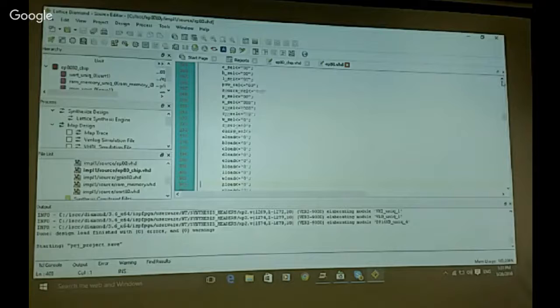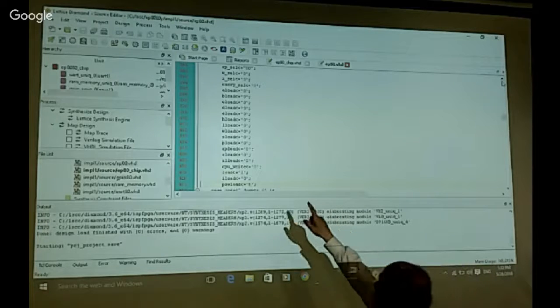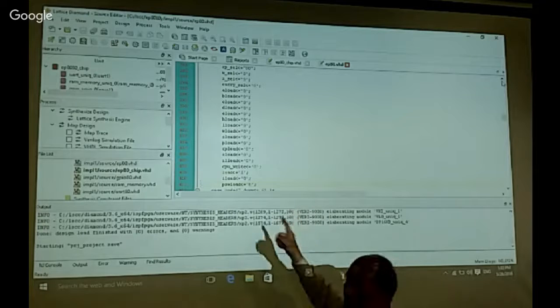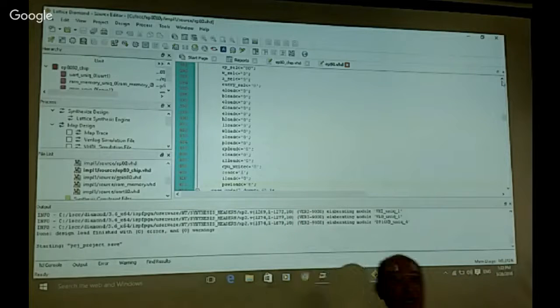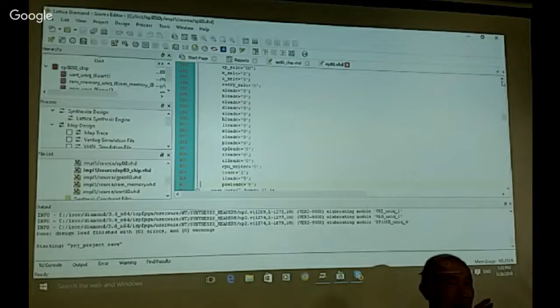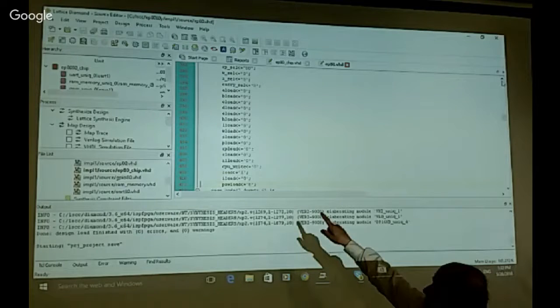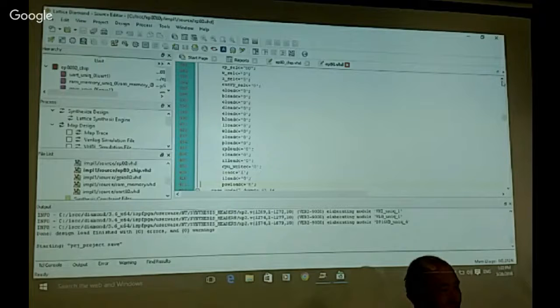And this load signal: every register has a load signal. If the load signal is at 0, the register doesn't get changed. If you need to change any register, that load signal has to be set to 1. So this is what an instruction does: it sets the proper load signal to indicate which register needs to be updated, and then sets the select signal to route the proper signal into the proper register.